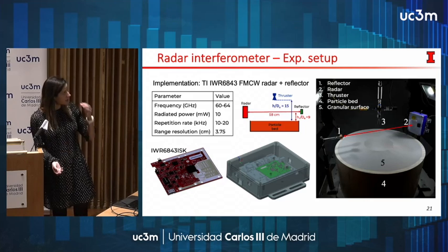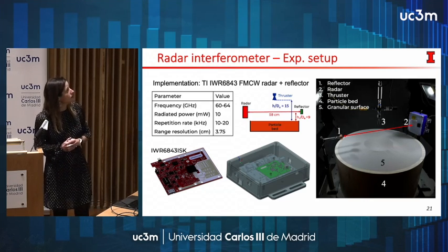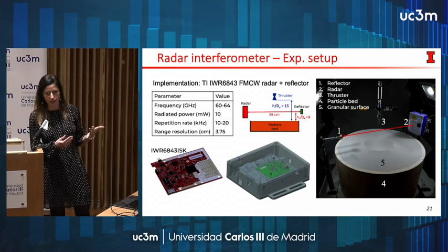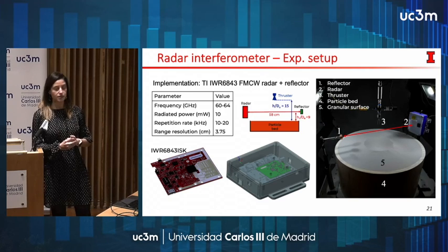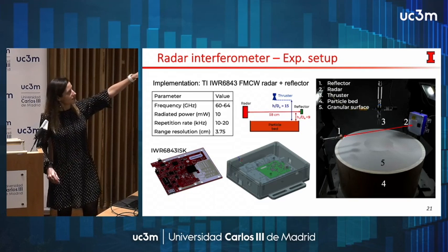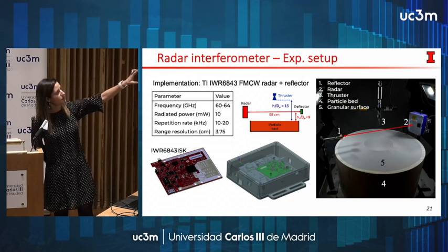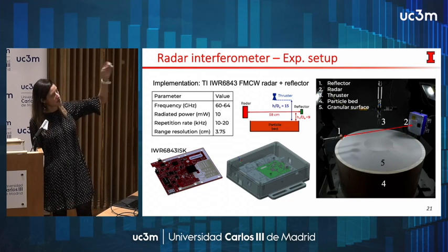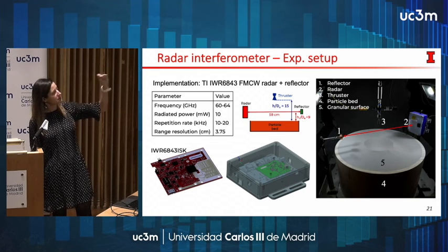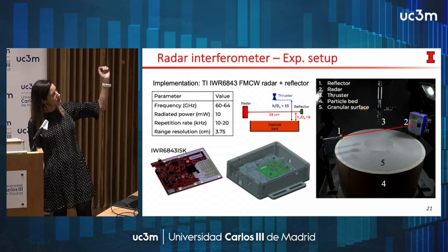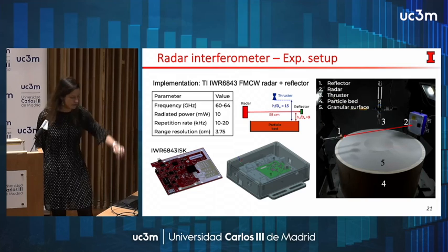So we actually tried this. This is the setup. It's actually a highly temporally resolved measurement, so we are doing it at 10 kilohertz. We could push it to 20 kilohertz, depending on how much you spend on your radar system. The blue box in there has a protection casing for the particles. It's our emitter and receiver, and we emit a chirp of millimeter waves that reflects on a reflector, and goes back as we blow the nozzle and form the crater.